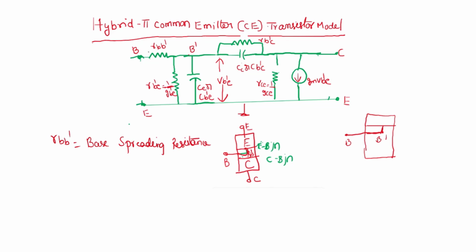When you are going for H parameter model analysis, we know all the capacitors are open circuited. That means the blocking capacitor CB, coupling capacitor CC, bypass capacitor CE, and also the junction capacitors CB'E and CB'C are all open. Totally 5 capacitors are open. No one is there to stop any current or voltage going into the transistor at the junctions, because the two junction capacitors are open.